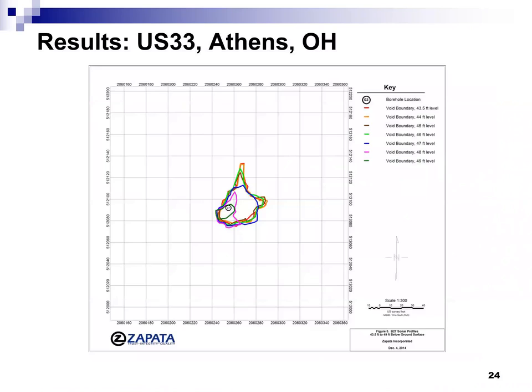Or we can do another line next to it, right? So let's... How close? One diameter away from the void. That's what we did in the 3D analysis. If we can put a sensor one diameter away from the void, we still see it, like a 3D effect, because we use a plane wave, so it's still visible laterally a little bit. So within one diameter from the center of the void, we still see it, interestingly.